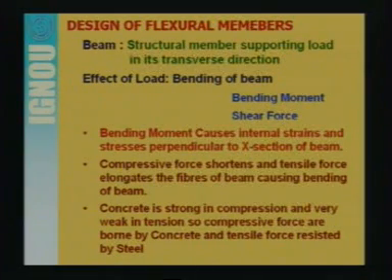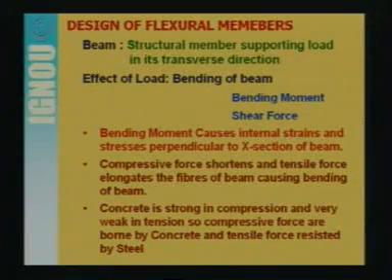The load is coming transverse to the direction of the beam. What is the effect of the load? The transverse load on the beam tries to bend the beam, which means bending of the beam takes place. Due to the load, bending moments and shear force come into the picture. So, the beam will be experiencing the bending moment as well as the shear force. The bending moment causes internal strains and stresses perpendicular to the cross section of the beam.